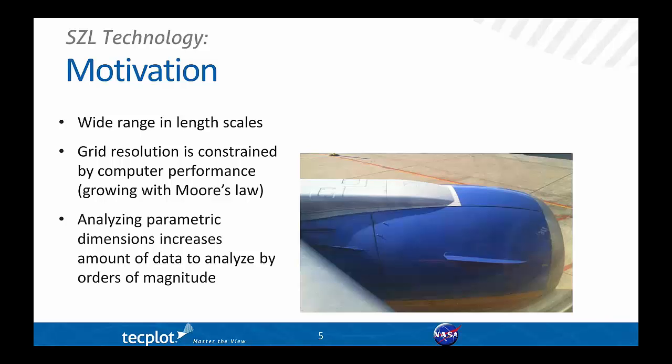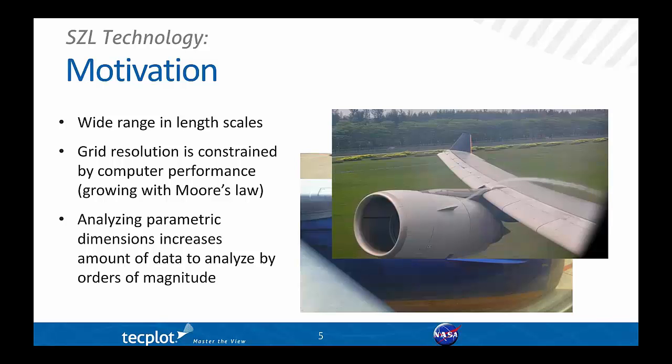And that fence is put there on purpose by the aeronautical engineers to control the aerodynamics at high angle of attack. So here you can see another picture out of a wing of an airplane, and the moisture is such that you can see the vortex coming off of that fence.